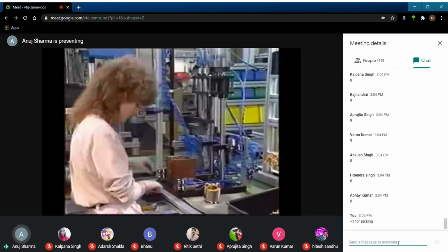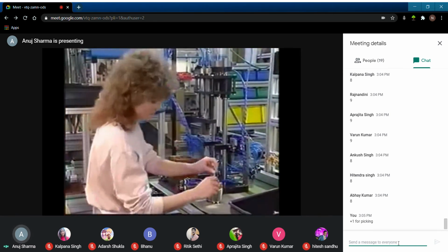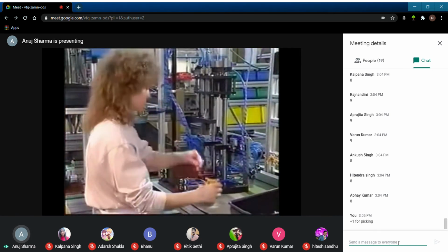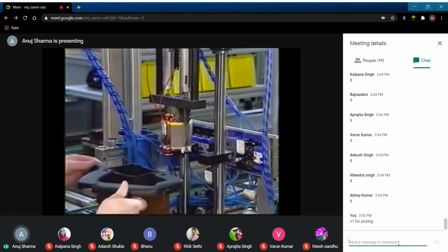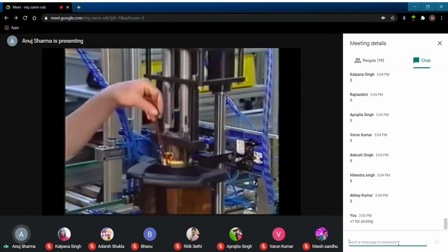At this workstation, 2 vane motors are used to drive pneumatic screwdrivers for the assembly of electric motors. One advantage of pneumatic motors is that they can be used for applications in which a maximum torque should not be exceeded.